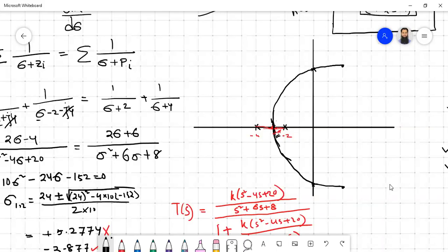Okay, so then we have to figure out the point through which, if the locus goes, it will maintain a 0.45 constant zeta line. Actually, it is also related to the percentage overshoot that we have seen in the last example. So 20% percentage overshoot. So we already calculated that for the last one, that theta is approximately 62.8, or basically 63.